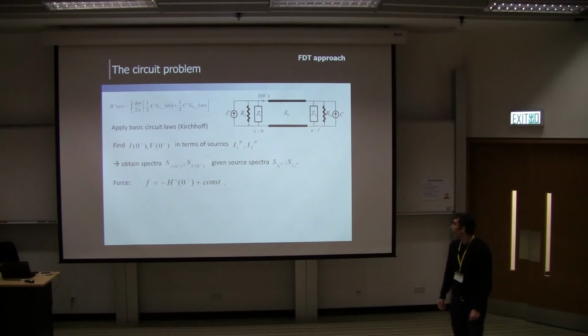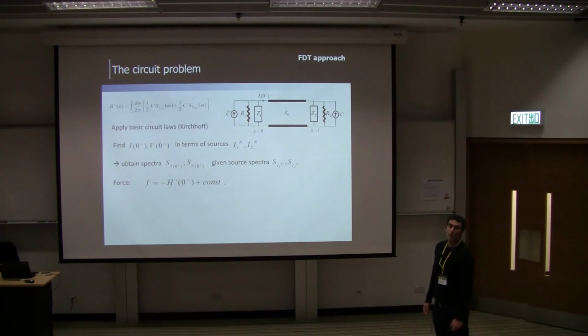Because no current will flow through your... My what? The top transmission line and the bottom transmission line, there would be no current, as there's no current flowing through. This is why you have a reflection of -1, because if you cut them, it means that the current is 0. If the current is 0, it means that you have a 0 boundary condition for the current wave. And this is exactly what gives it, like in a metal.